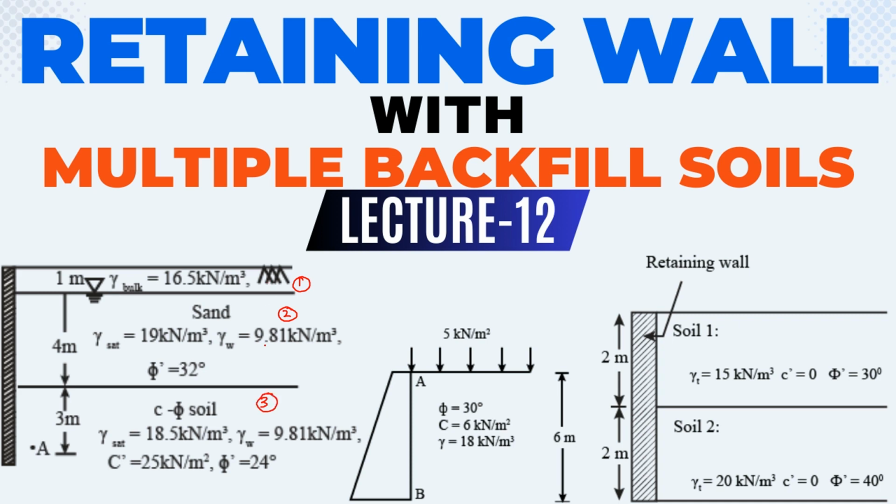So here there are three soils acting as a backfill because the unit weights of these soils are different from each other and their friction angles are also different. So if a soil has a different friction angle and unit weight, the soil will have a different pressure or different stress on the wall.